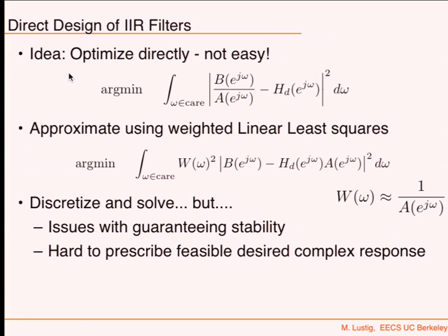And so here's the idea. We did the same approach in the FIR filter design, where we had some optimality criteria or some difference criteria that we'd like to minimize. How about we also impose it on the IIR? In the IIR, we effectively have two polynomials in the Z-transform that we would like to design.